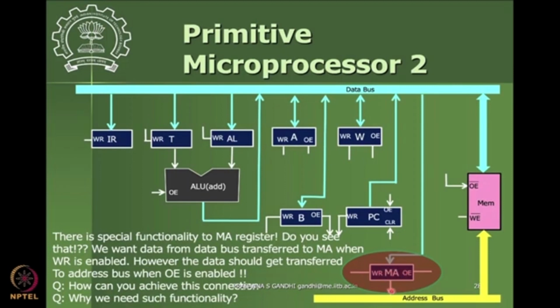That address will then be on the address bus, pointing to the particular location where your program is written in memory. Now the first command of the program can be fetched from memory onto the data bus and transferred to the instruction register.